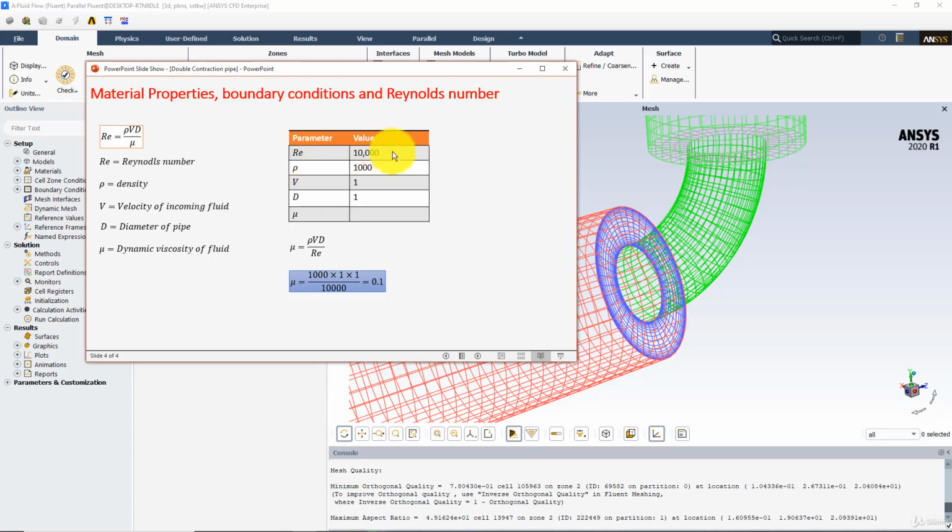And we don't want to be just on the edge of that Reynolds number range, so I put the Reynolds number at some higher value than 4,000. My safe bet is 10,000. And I'm taking density as 1,000. It's your choice. You can take any value, but as long as the Reynolds number is the same, the results will be the same. It's a liberty of CFD that you can put any value for the material properties, which is not an option you have in wind tunnel testing or in the lab.